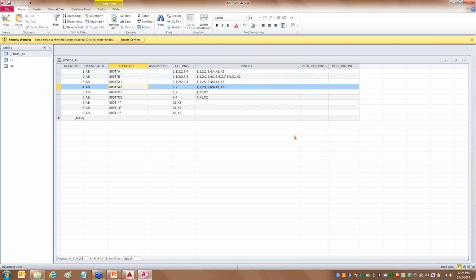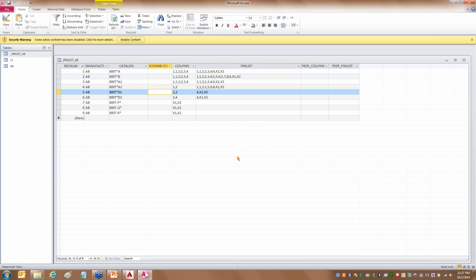So I went down through here and I've got these all set up. Here, this one right here is a 2 normally open pin setting, and that's the only option. So I only have 1, 2 because normally open is my only choice. But here I have my 2 pin settings for normally open. This one being only 1 normally open, so all I have is my coil pins here for the parent, and then I've got a child where I can connect a light to it. And so you can kind of see how that's working.